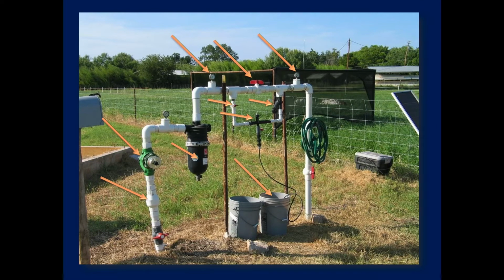The next thing you've got is a pressure gauge, obviously, because you want to see how well this is working if you knock down the pressure. Normally, when you inject something, you want to maintain pressure as high as you can until you actually inject it. Then right at the point of the field where we've got the drip lines going out, that's where you want to knock the pressure down. So you always want to try and maintain as much pressure as you can until you actually get out into the field. I'll show you what that looks like here in a second.